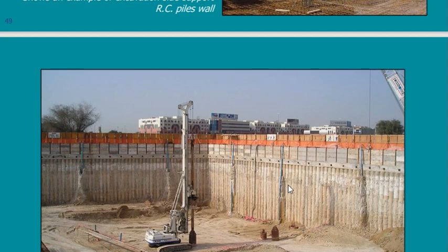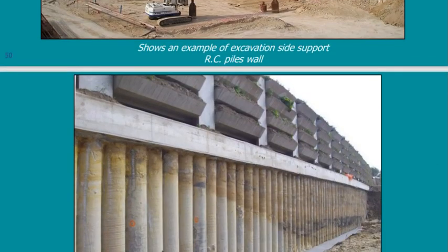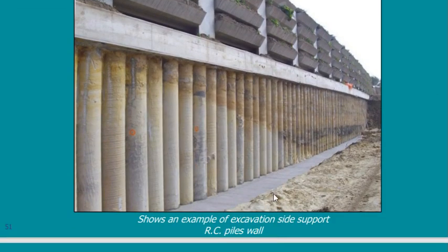Usually if you look at the piles after construction, you find deviation and angles, piles inclined with 5 degrees, 4 degrees, and so on. This is bad construction. But here, this is a very good type of construction. Piles are very close to each other, and they could excavate inside very easily. You see this shape, very, very good.